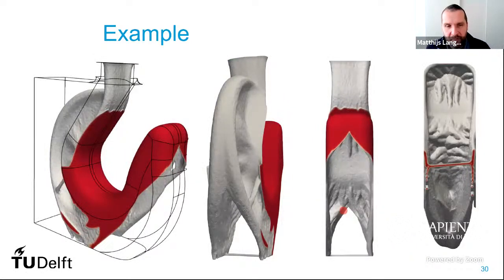And here is a result of this process. I think it included something like 30 million degrees of freedom. So this was really a good test of seeing how the scalability was. I think per iteration it took in the order of a few minutes, so that was still doable. And you can see that the technique to control overhangs has worked well. So here we can see, for example, a typical shape that you get when you are dealing with an overhang restriction. This is viewed from below, so here you cannot easily recognize that, but the end result did not contain any critically overhanging surfaces.